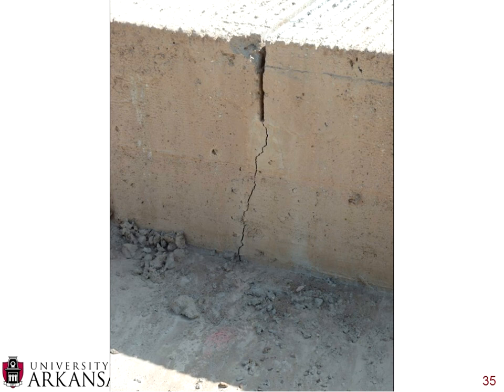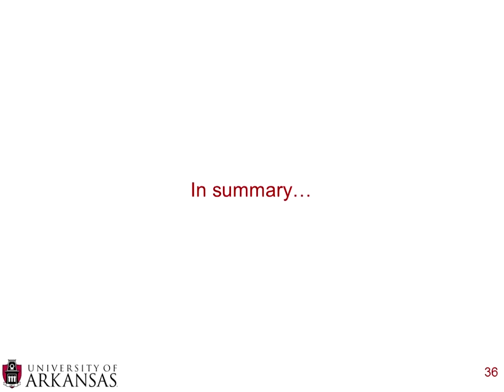But I did want to show this very nice picture of a nice joint that was cut and then the crack that developed. This is why you want that larger aggregate, because that crack that developed below the joint is going to have load transferred through the aggregate interlock, which is critical for good pavement performance, especially if you don't have dowel bars.